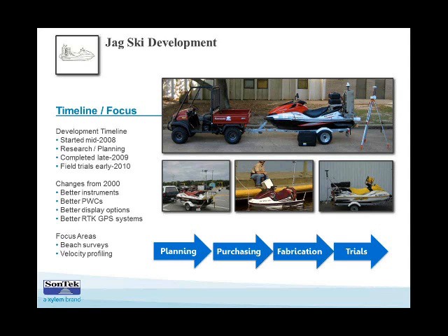As it turns out, if you're going to go out and do ADCP profiling, either for a bathymetric survey or for velocity or discharge profiling, you really need calm conditions to get quality data, so the conditions don't become so much of a factor for the personal watercraft. So if it's a calm day, conceivably you can go as far offshore as you want. We generally only go about 1.5 miles to 2 miles offshore, which gets us to a depth of about 10 to 12 meters. That's generally about as far out as we'll go.